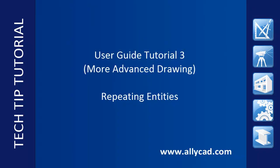In this tutorial, we will discuss duplicating entities using the repeat function. The repeat function allows you to duplicate entities a number of times with a specific distance or angle between them in either a rectangular or a polar format. If you've not already done so, check out our other tutorials.